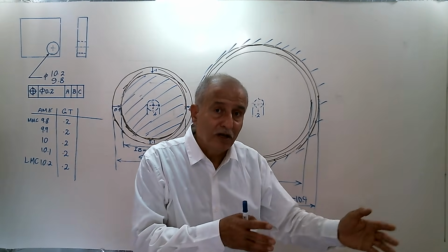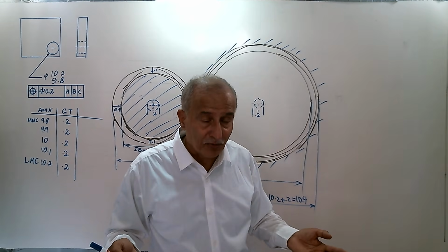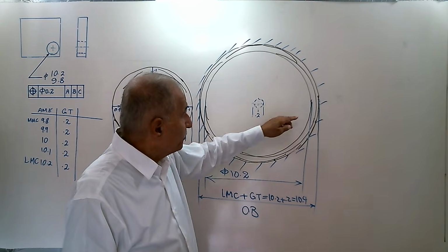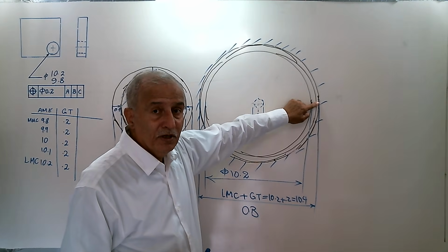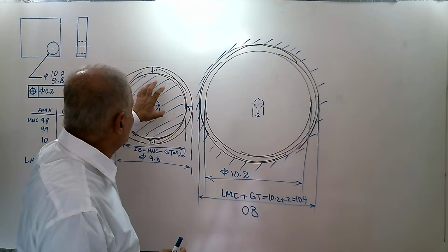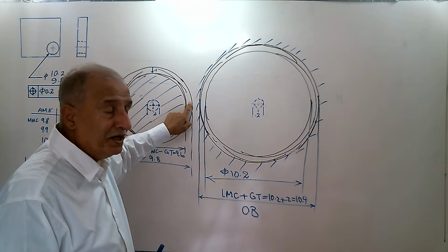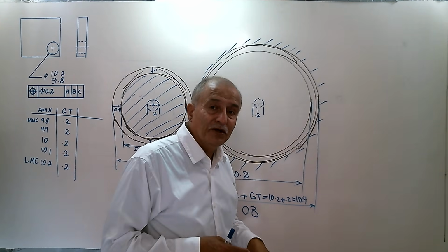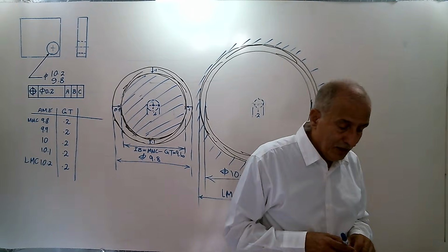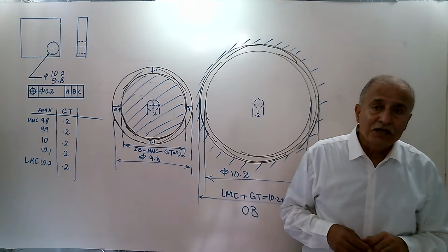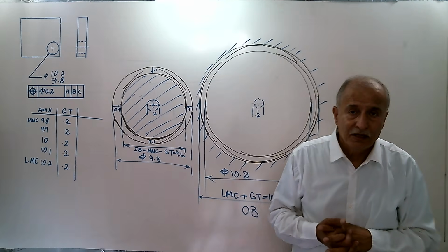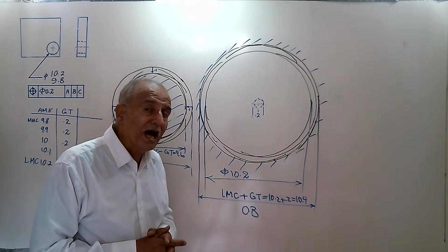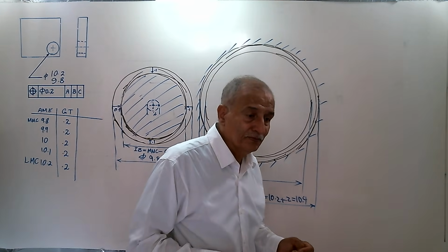Hole can be shifted, hole can be largest diameter, and also can be shifted. Then in this case, it approaches this border. If you think that, okay, the hole is here, I want to construct another part here, it will actually interfere with the border and keep out region of the hole. Okay, that's the inner boundary and outer boundary for position tolerance of a hole at RFS.